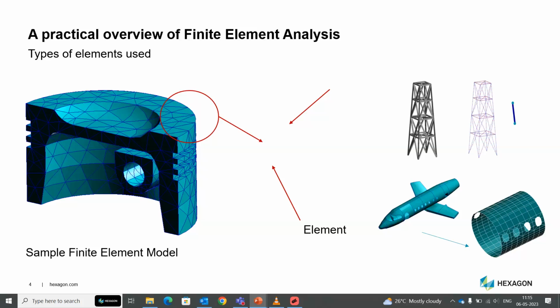You're utilizing a similar principle. And with the advent of digital computation, it helps you analyze this using a computer program. You're basically going to compile this and ask the computer to solve this matrix equation in order to get your unknowns, which are your stresses and displacements.